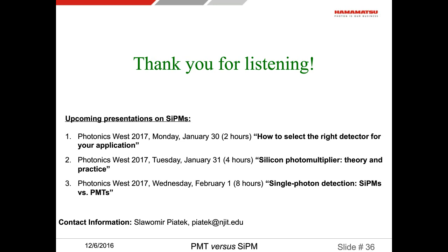Okay, here's an interesting question. Do you foresee PMTs becoming obsolete? I do not. The example of bioluminescence and chemiluminescence is a situation where PMTs clearly outperform SiPMs. The large active area, the low output capacitance, which I did not stress in this webinar, and very low dark currents are simply superior for applications of this nature.